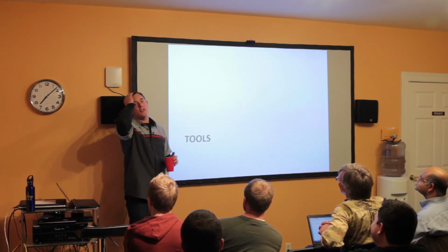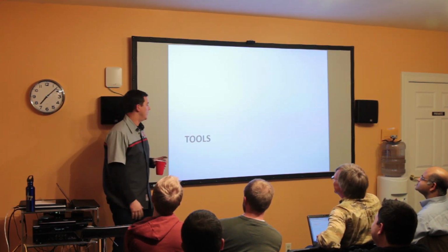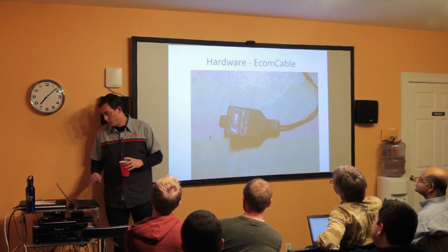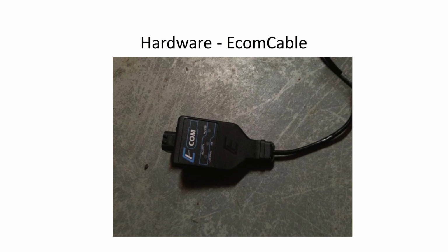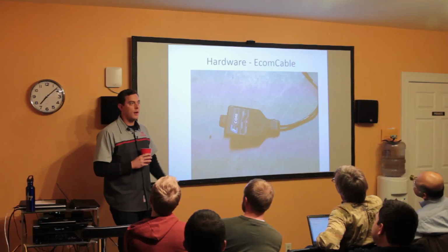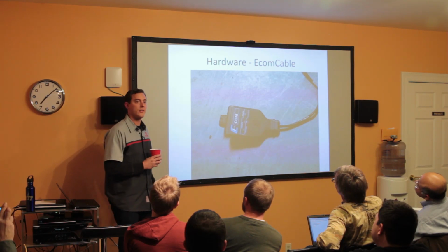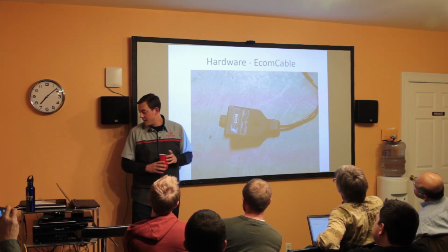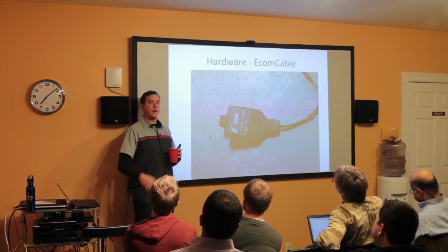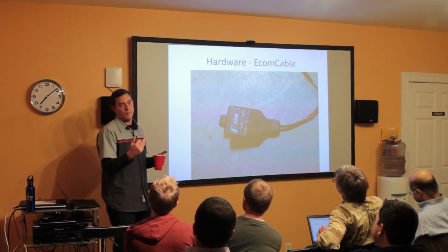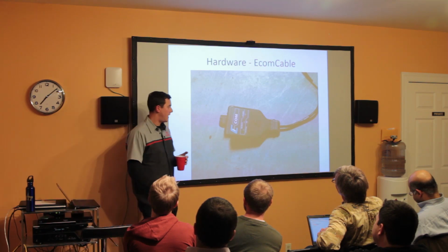So we went through Canada standards and all the services that could be used. Let's talk about some tools we used. I actually brought this with me. This is an ECOM cable. There's a company called eControls. They're super nice people. Their support and engineers actually contacted us. It basically has a nice Windows API to do reading and writing of the CAN bus. So it was nice that I'm really familiar with Windows.